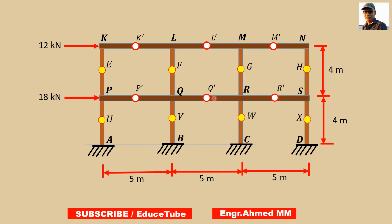Now to compute axial forces in the columns, say in this story, we will first pass an imaginary section through this hinge. And the free body diagram of the portion above this hinge line, I mean this part, we'll take it and we'll see it in the next slides.